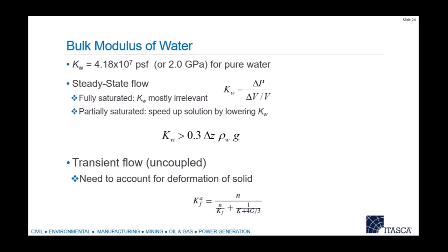If you're doing a transient analysis and timescale is important, but you still don't want to use the full fluid modulus because then things take forever and your time steps are tiny, you can still play games. What's important here is the ratio of the mechanical stiffness to the fluid stiffness, so that you're not completely out of range of reality. So then we have a different rule of thumb. We adjust things according to this relation. And again, I'll cover it more later.